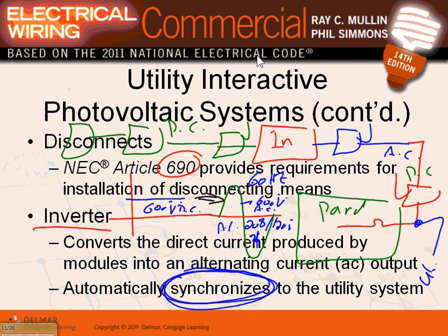So here's a little key component for this particular one, guys. Suppose that this is my voltage coming from the inverter, and suppose that my utility voltage is something like this. This is my utility. I need to be able to synchronize them, guys. Grab them together and match my voltage with the grid so they can lock with the grid. Otherwise, you know what happens if you don't lock them together?